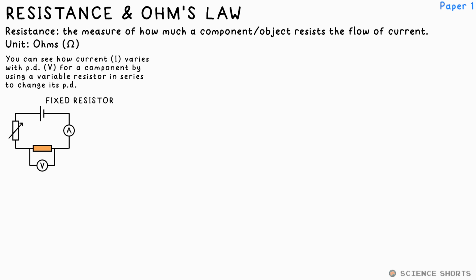If you make a circuit with a resistor and change the PD available to it, what we find is that an increasing PD results in a greater current flowing. In fact, doubling one doubles the other, so we can say that PD and current, or V and I, are directly proportional. Drawing a graph of these two makes a straight line through the origin, and if we turn the battery round, we can get negative values for both too, but still a straight line.